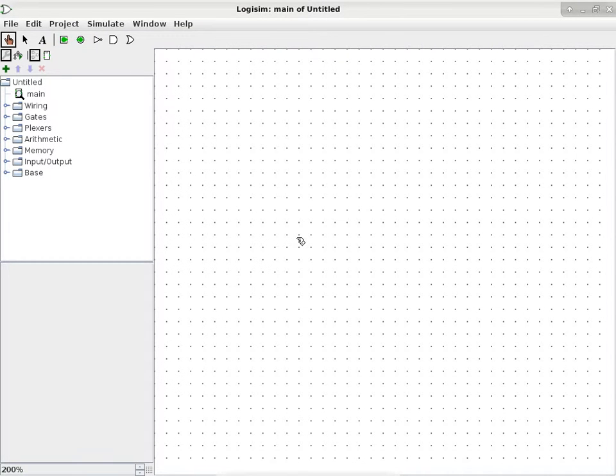I also got one question where Logic Sim does not seem to be working correctly. Well, chances are it is not working correctly. So if you think Logic Sim is doing something funky, that it's not supposed to be doing, save your file and then close Logic Sim and restart it. Because occasionally Logic Sim does lose track of the work. It will mark something as incorrect when it is actually correct, so just close and reopen it. Most of the time that will fix the problem.